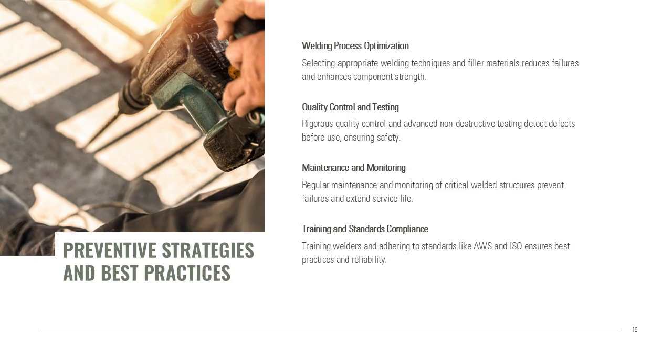Preventing failures in welded steel components requires a multifaceted approach. Key strategies include selecting appropriate welding processes and filler materials, controlling heat input to minimize residual stresses, and applying preheating and post-weld heat treatment to refine microstructure.